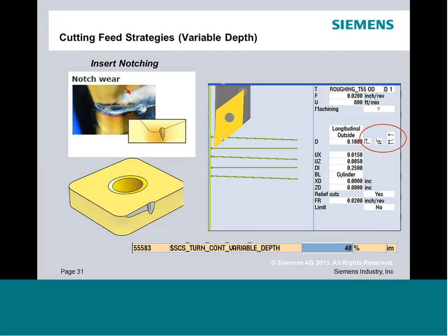Just like you see this little arrow on this insert right there. Over time, hitting at the same point, you'll actually get more wear at that point than you will at the cutting edge, and it will cause this insert to prematurely fail. So your leading edge insert, which everybody always thinks of as the area that's going to break down the worst, isn't necessarily the actual portion that causes the insert to fail prematurely. And you can even see I have a little picture here of an actual insert that's showing you a heavy chip notching that occurred.